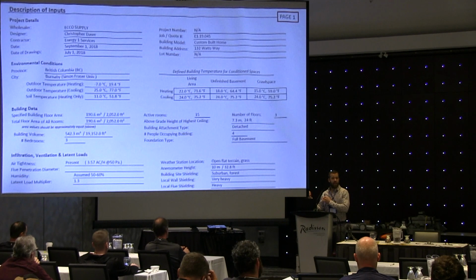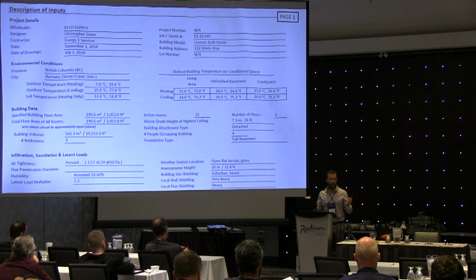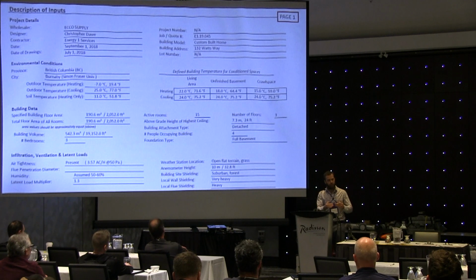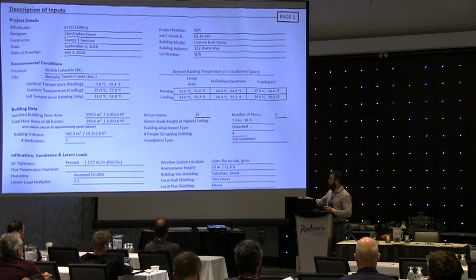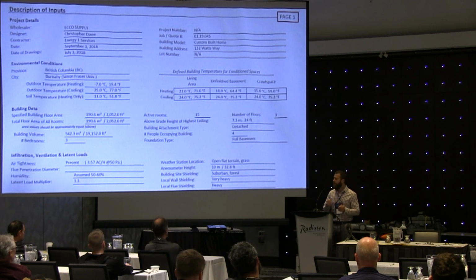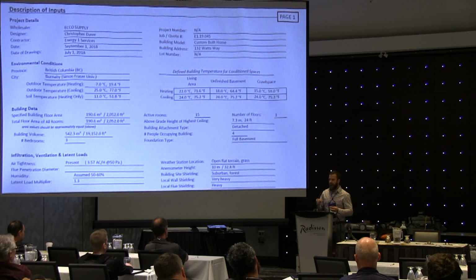When you're doing this to size the appliances, you would never have an air barrier up and blower door test results already. So maybe you know the builder, you know approximately where they build to, and you would input something like that. If you don't know the builder, you might choose one of these preset values. So there's 4 preset air tightness levels. I think they are average, present, energy tight. Anyway, there's 4 of them, and they vary from like I think 10 air changes per hour down to 1.5 air changes per hour.